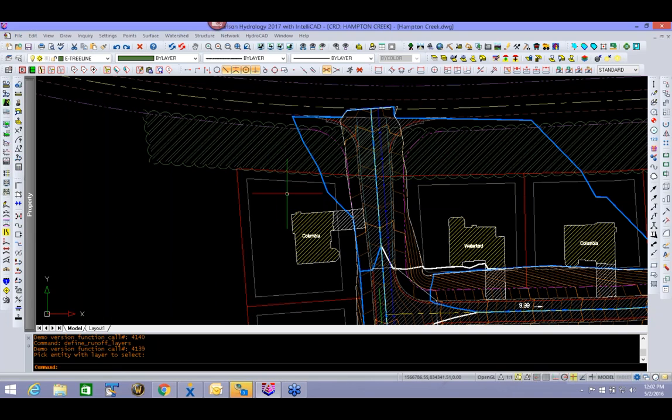The reason that we use closed layers and closed polylines is because if it doesn't hatch, it's not closed. So it's kind of a graphical representation for you to see. This is the very beginning thing that you want to do in your CAD design, that you've already got this information, so you can create these watershed layers for your storm drainage runoff.